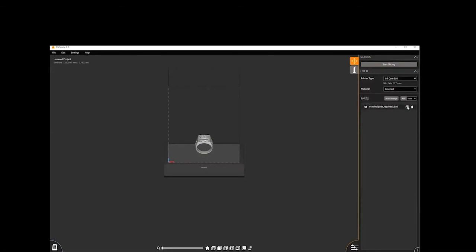You have a duplicate button, which I'm going to click now. When you do that, that will automatically add another part to your build table. You can also delete your parts from here by hitting remove. You do have to click it 2 times. So you click it once, it will give you a check mark, and you have to click that check mark before it disappears, otherwise you won't delete it.